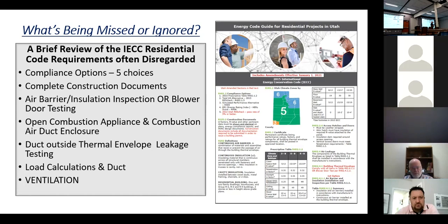Does that help? What's the reasoning behind having the duct in the attic? I just was down there, met with DR Horton. They're a national home builder. And when they started building down there, everybody told them, the subs, everybody says, oh, we just put them all in the attic. And they said, well, why? Because that's the way we do it. They build generally slab on grade. They don't have a basement. And so they don't want to give up any floor space for mechanical.